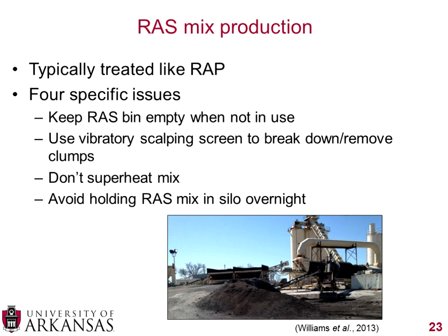Another thing is that you would like to use a vibratory scalping screen to break down or remove any clumps. Even when you're transferring material from the stockpile to the bin, you would ideally like to have a vibratory screen on there to break down any clumps, to avoid getting any of those agglomerated particles into your mix. You certainly don't want to superheat the mix.